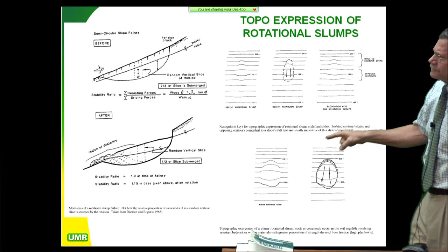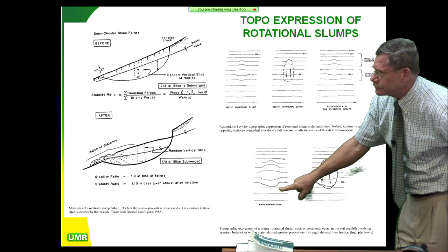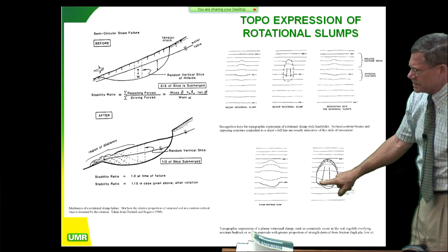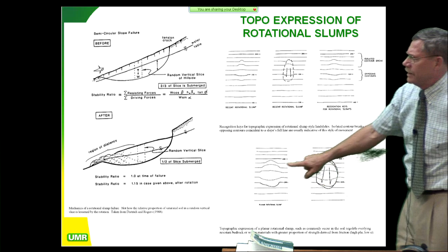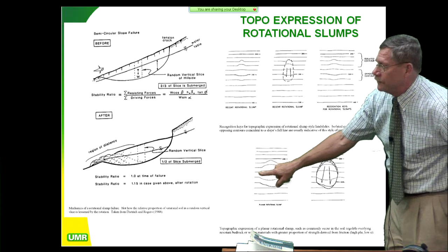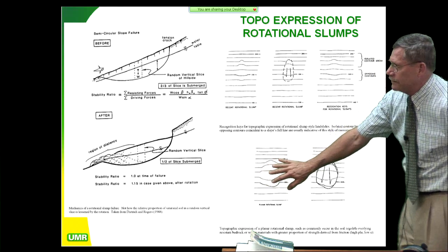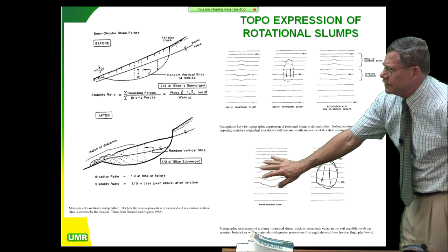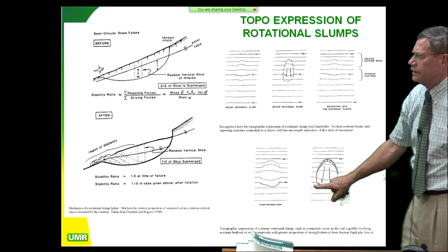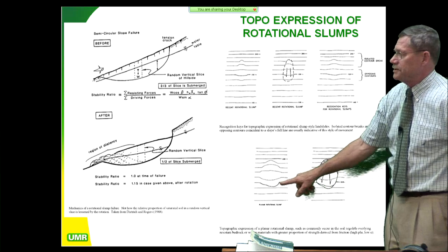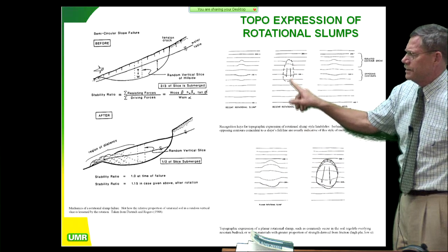So if we look at something more planar, more pancake shape, this is the high phi material. So we get more of this pancake shape if we get a phi angle up above 40 degrees or something like that, or we just see the soil regolith above the bedrock that's involved in the movement. We get a more pancake-shaped type failure. Sometimes these are deeper, sometimes they're shallower.